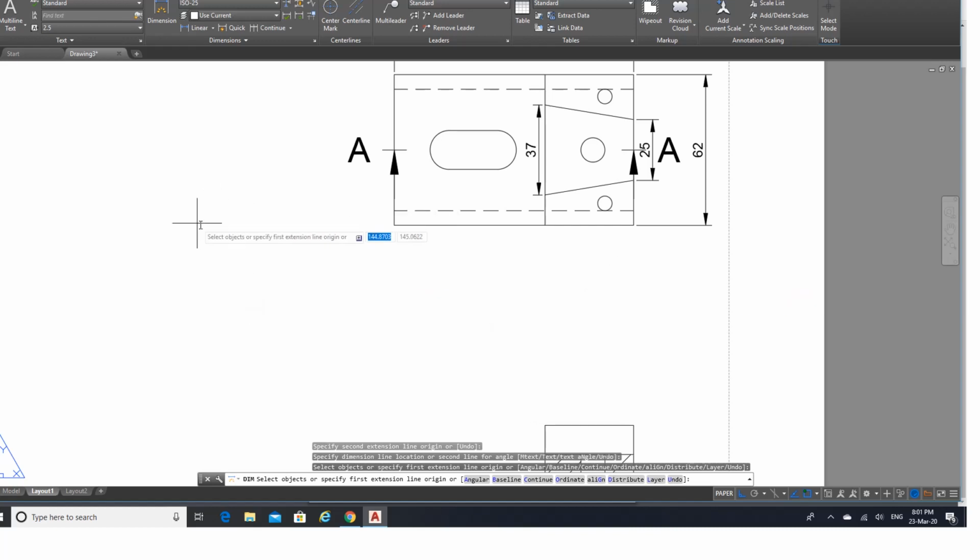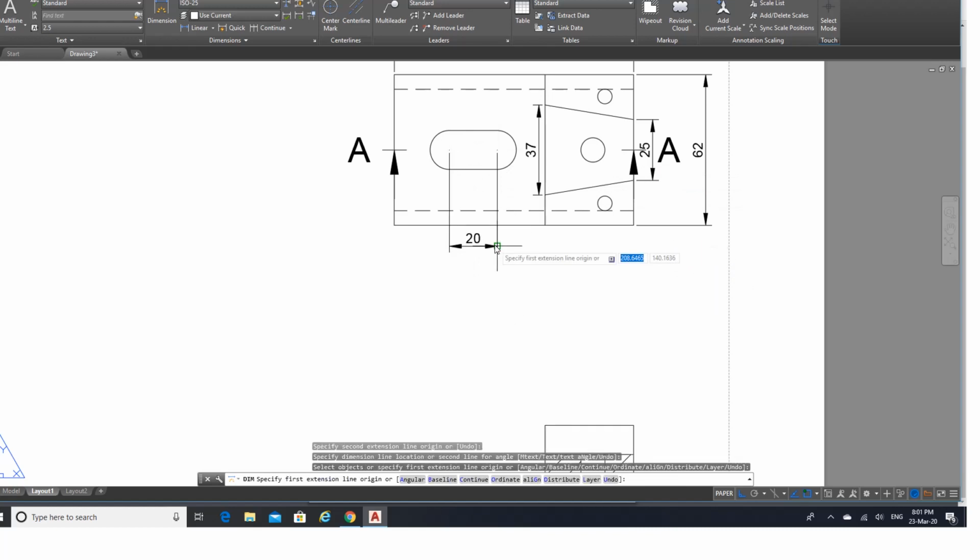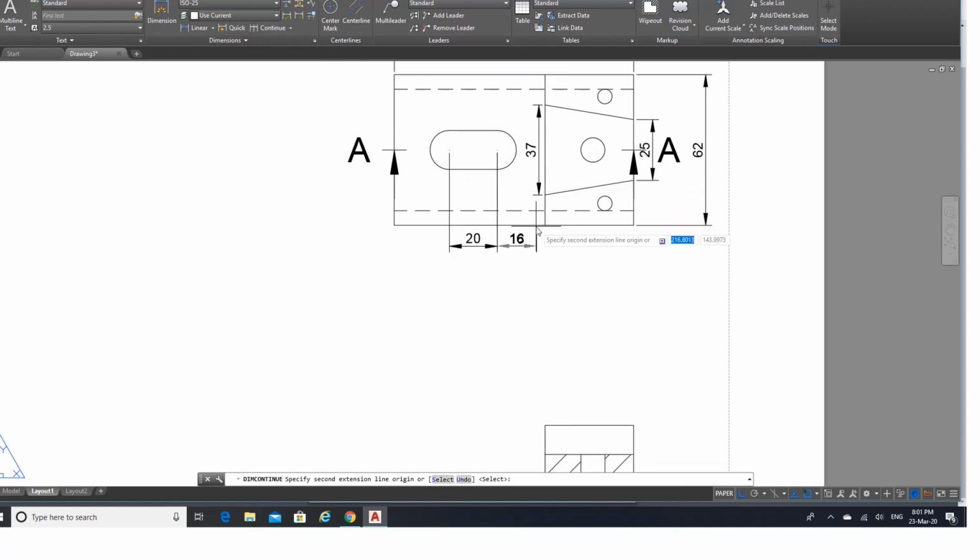I need for this one. Sure. So go select the center point. Where is the center? Center of the circle is here. Okay. You go here, center is taking here, center to this circle center. Sure. How much is this? This is 20, and then just say continuous dimension, so it will catch from here, go here 20. Okay, and then what about this one? This is 37. Great job, enter.